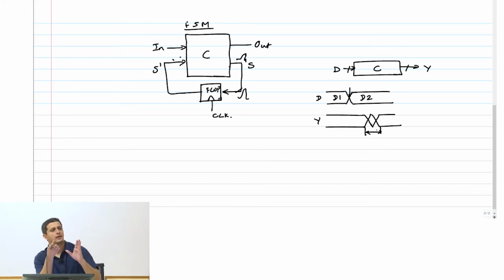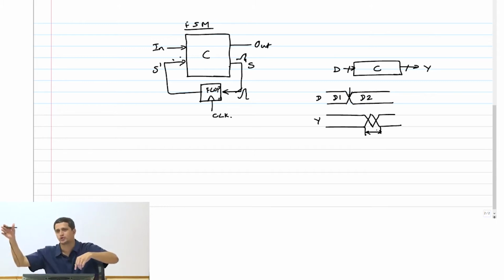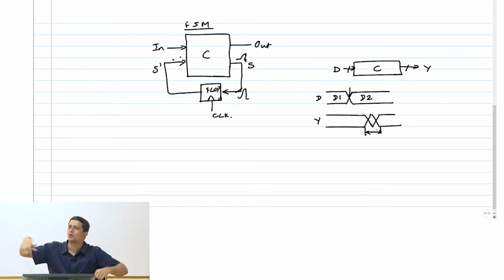For example, when one input changes, I could have some short path through my combinational block which causes one of the outputs to change. But now when another input changes, it may come and overwrite this. There is a possibility that you'll have a glitch at one of the outputs, and that glitch is what we are capturing here. The issue is the glitch can affect the circuit going forward. So we have to make sure that the earliest change of data also we should be very careful about.